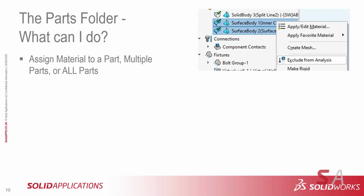So you'll notice that the model I made up for demonstration purposes here is a multi-body part file with all different kinds of bodies in it. And the study tree doesn't really make much of a difference, doesn't really distinguish. It just looks at it and says, these are all the bodies I've got, and this is what kind of body they are. So when I say parts, I'm not referring literally to parts, and you'll see that in the demo data set that I have, which is all one part, but many bodies.